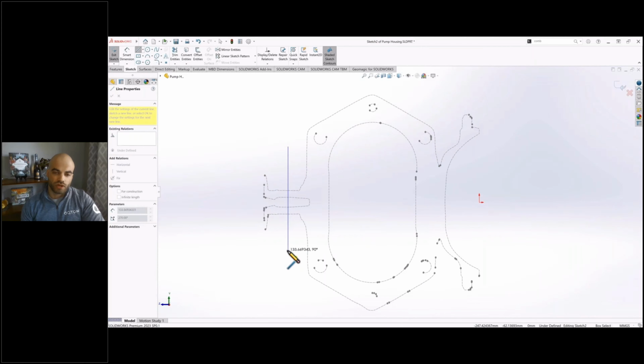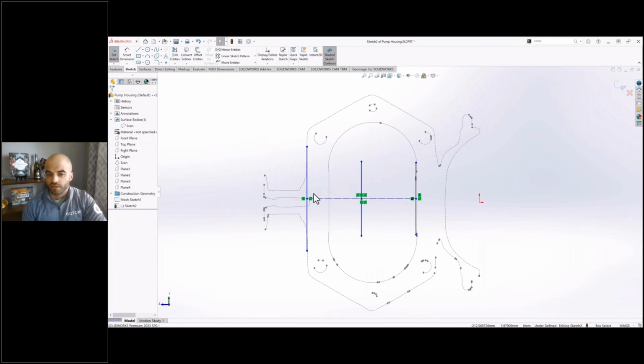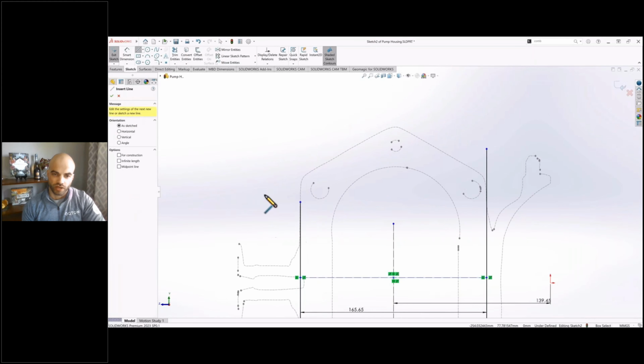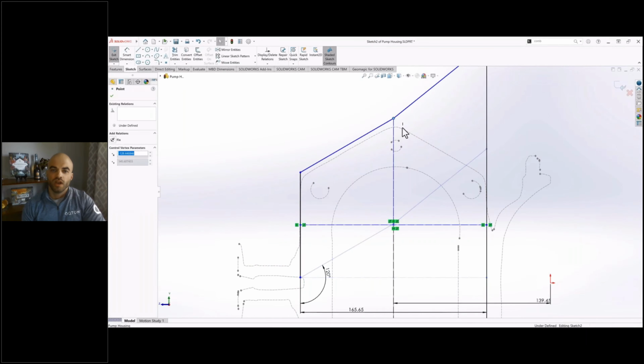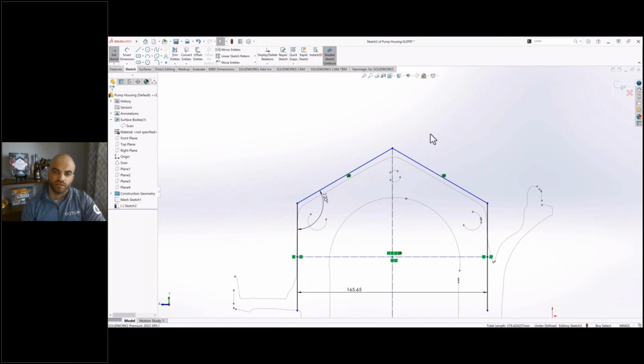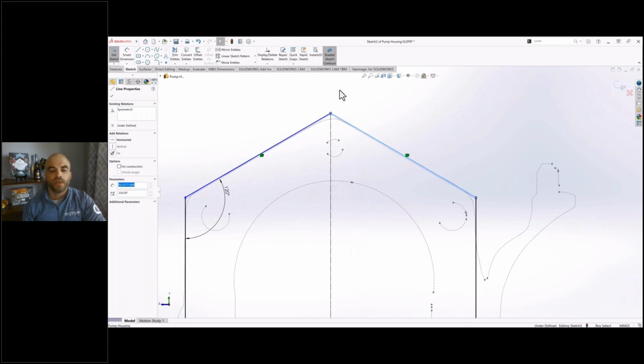So here's where we'll start speeding things up, because most people know how to sketch. But as I have different tips and tricks, I'll definitely highlight those. It is a little bit different of a sketching workflow versus your traditional parametric part, because we're trying to reference this scan data. So I'll pull some tricks that might give you the heebie-jeebies, like throwing on fixed constraints and snapping directly to these polyline splines here. But it's all part of the process to get this organic data to rein into something a little bit more perfectly parametric, right?